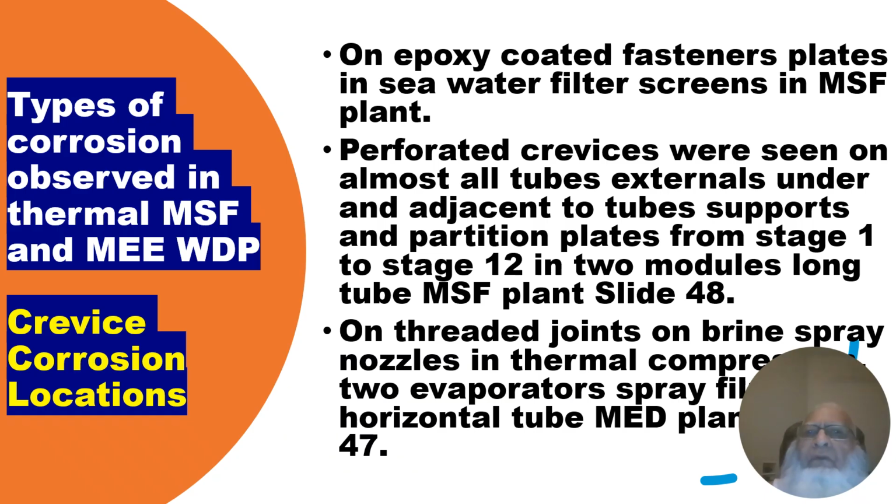On epoxy-coated fasteners, plates in seawater filter screens in the MSF plant, perforated crevices were seen on almost all tube sheets, under and adjacent to tube supports, and partition plates from stage 1 to stage 12 in 2 modules, long tube MSF plant, which is slide 48 as a part of the presentation. You will come to know the slide number when we reach that slide.